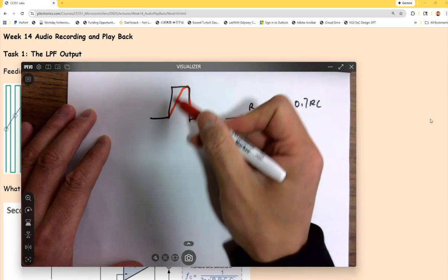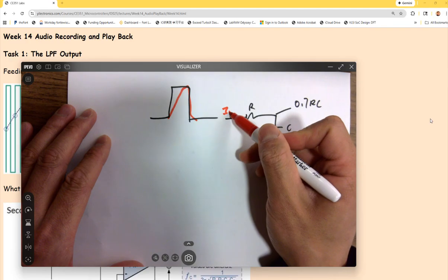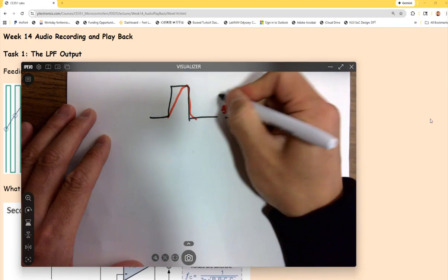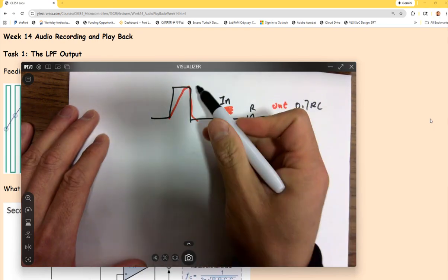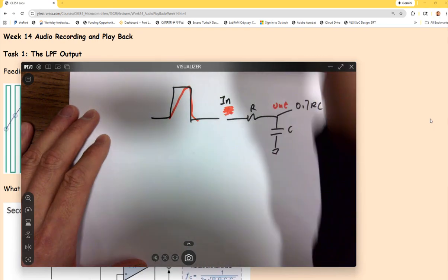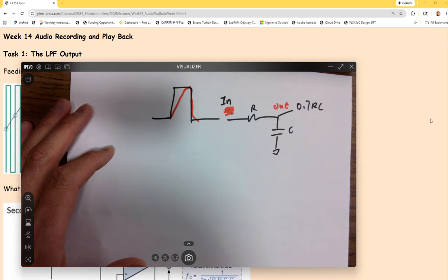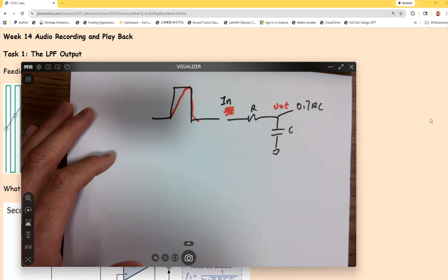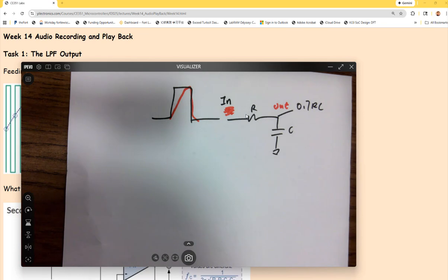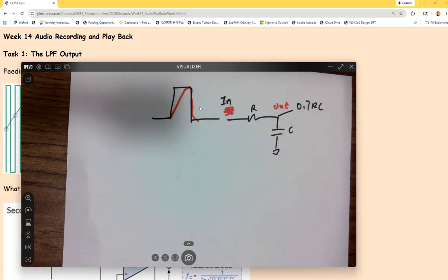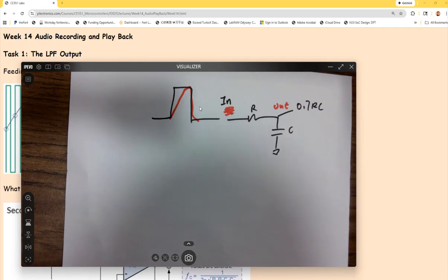So the input digital signal is getting delayed, right? No one can avoid that on the circuits. If you're not using superconductors, there will be time delay. Okay, there will be time delay. So parasitic resistance and capacitors are everywhere, and so time delay is usually a very bad thing to avoid. And you have to design your circuit very carefully. Try to improve the performance of the circuit.